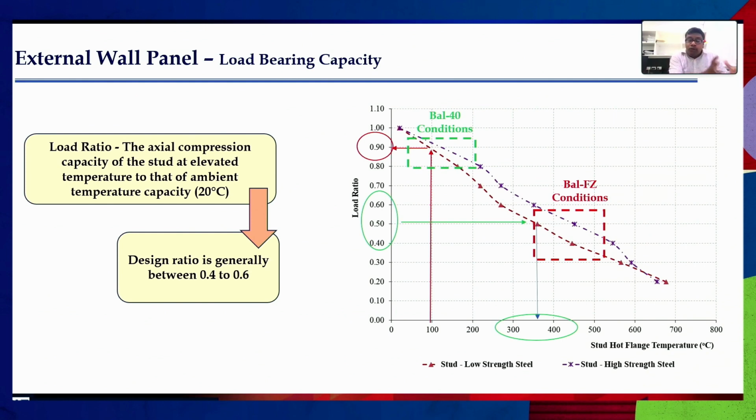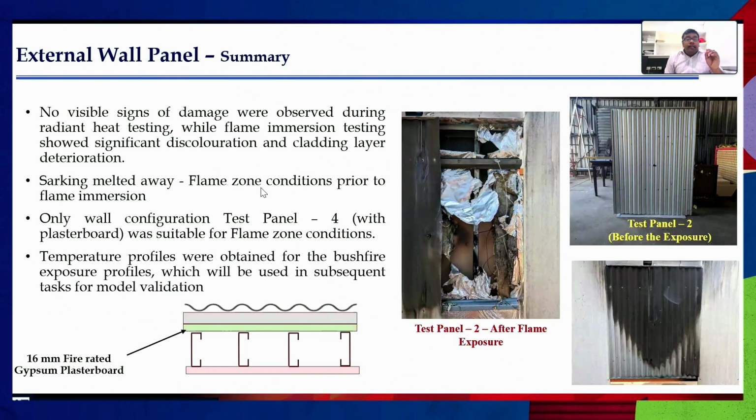So that applies to the steel cladding wall panel as well. That means we can still use that steel cladding to protect the steel stud from buckling.